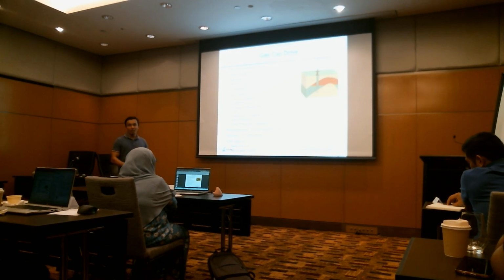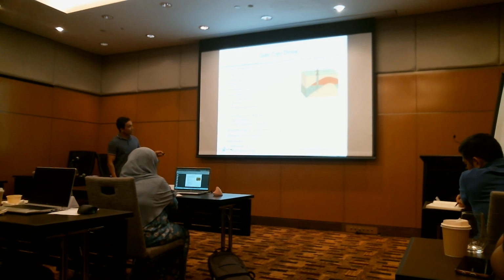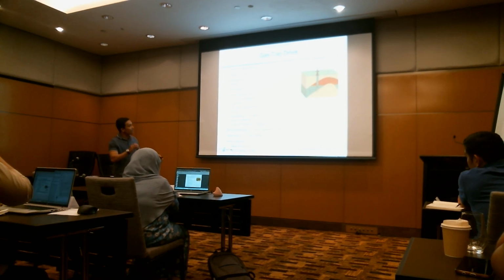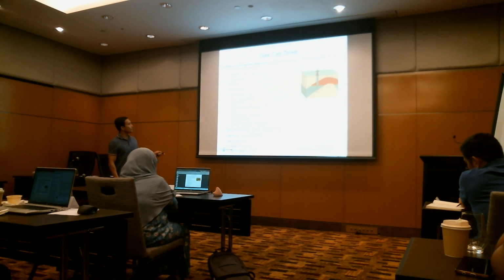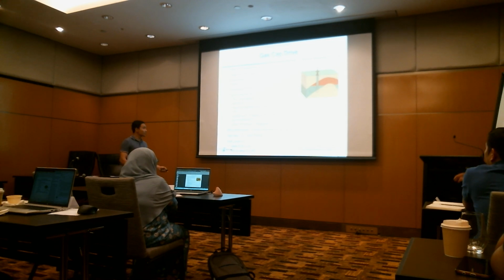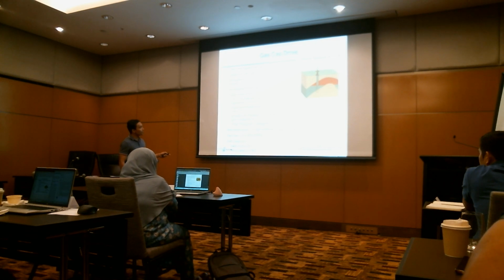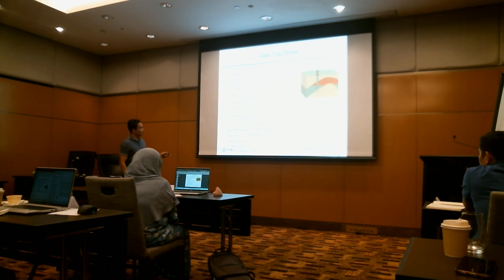Of course, because we have more energy as compared to solution gas, so you expect the production decline to be gentler. Pressure declines slowly depending on gas cap size. I mentioned earlier, it depends on M size. Initially, GOR is steady but increases rapidly later as gas bypasses oil. Okay, we discussed this one.